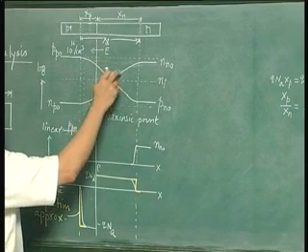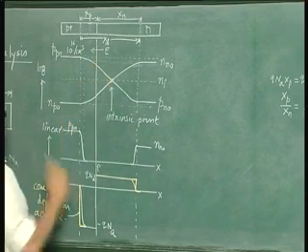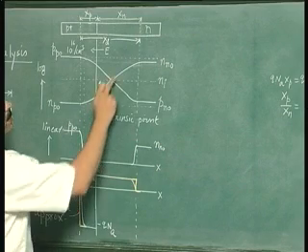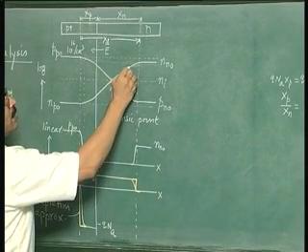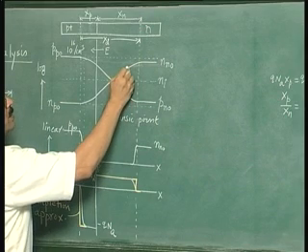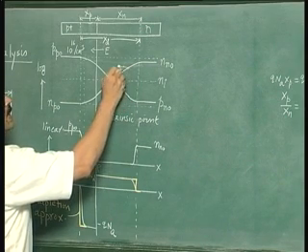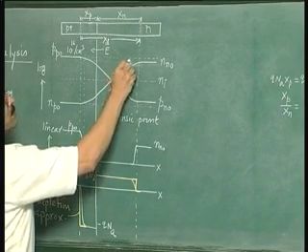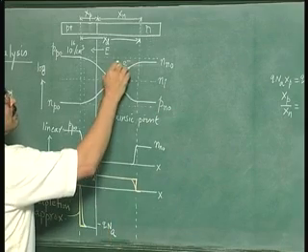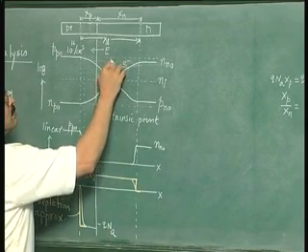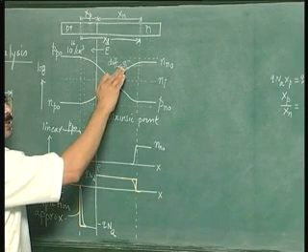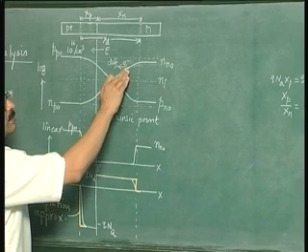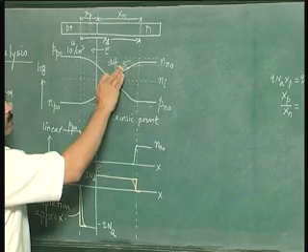So you have two types of currents, drift and diffusion currents. Now see what happens. If you take this point, at this point there is a gradient of electrons, therefore the electrons will tend to move in this direction because of diffusion. I am not showing the current, but I am showing the direction of flow of charges.